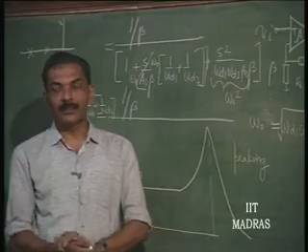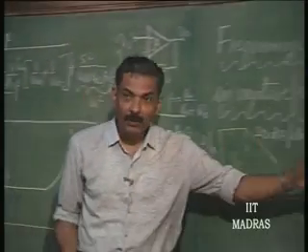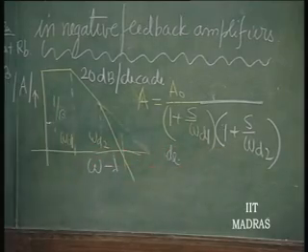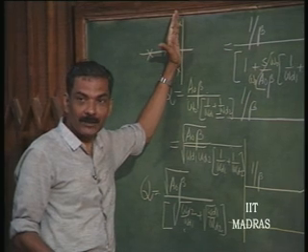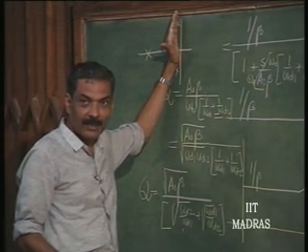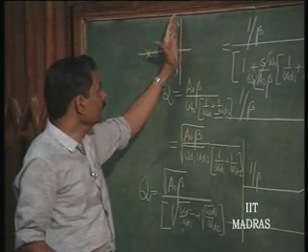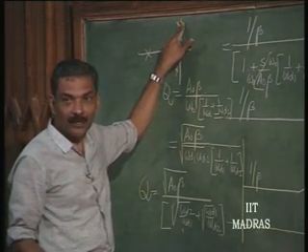Now, the type we have understood. That means, by the time the system has a second pole, the system is now going to be very nearly on the verge of instability, because if we now have additional phase shift caused by an additional pole, then this can shift to the imaginary axis and the system can become unstable.